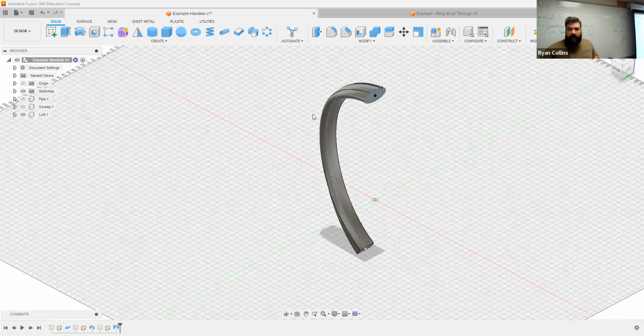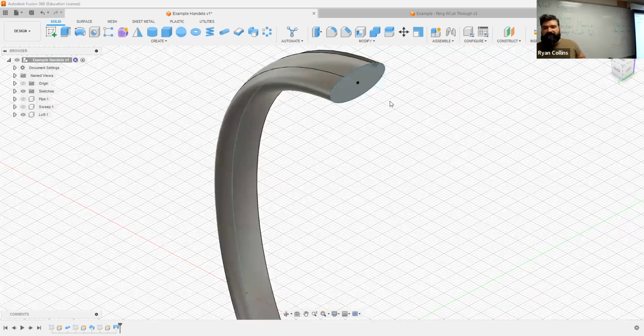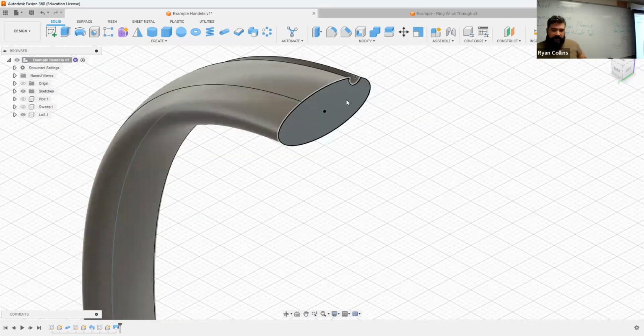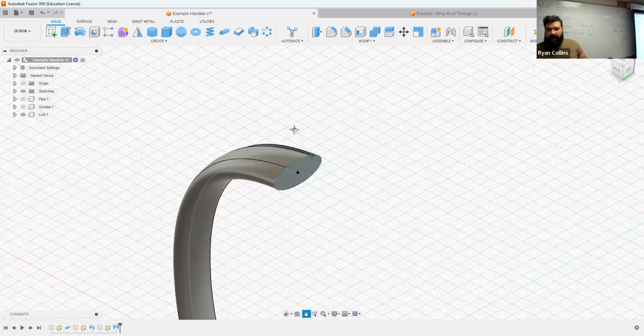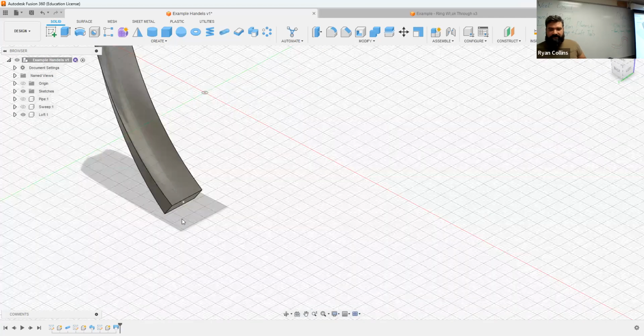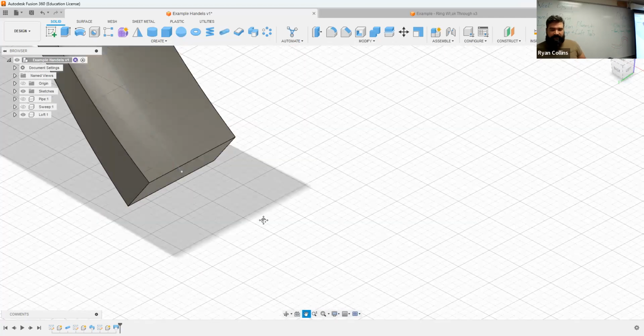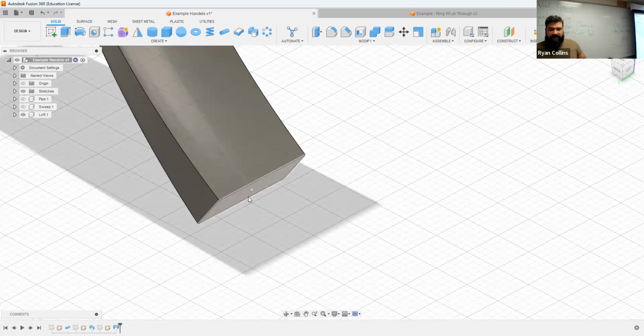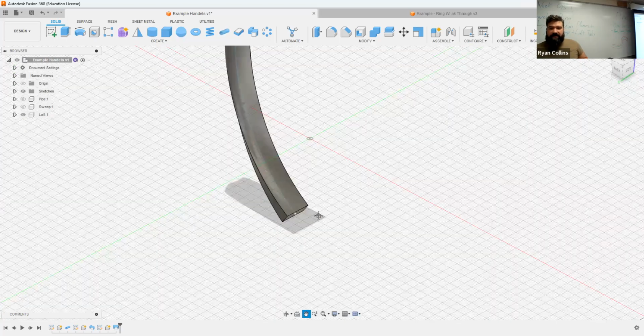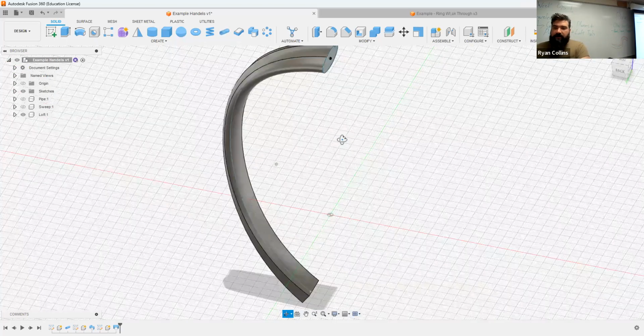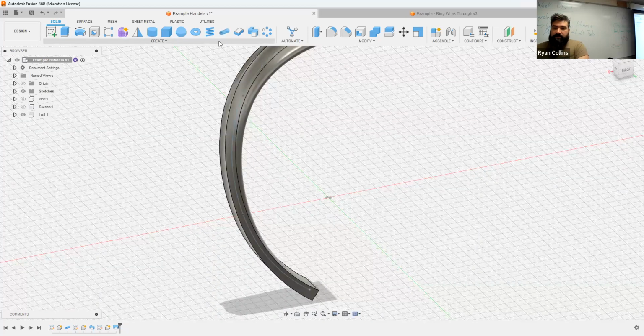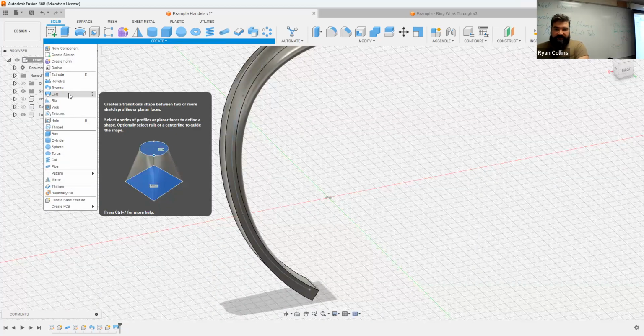All right, the last one I'm going to show you is a loft. Same deal, only in this case, I took the same shape, that ellipse with a notch in it, and my second sketch built onto the other end of the fit point spline, my path, is a rectangle. You can see how it transitions, as the Loft tool says, between one and the other. So you can take, obviously, a circle to a square.